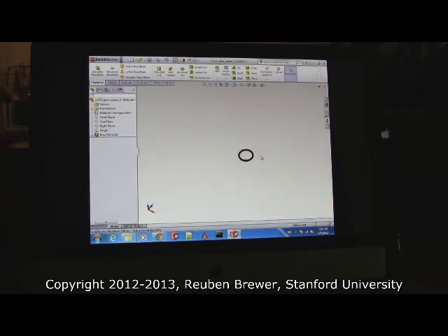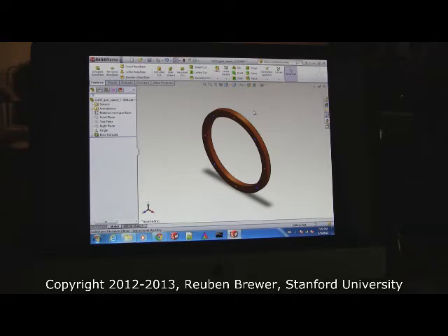Okay, now oftentimes SolidWorks just does crazy stuff. I'm just going to go ahead and zoom way out and I'm going to translate, and where did my part go? It's small, it's far away, it's scared and needs a friend, and it doesn't know where it is. And I can't find it. See, I'm rotating and I don't see it. When this happens, and it will happen many times in Lab 1, go up here and hit the isometric view. Boom! It's back. You learned a lesson.